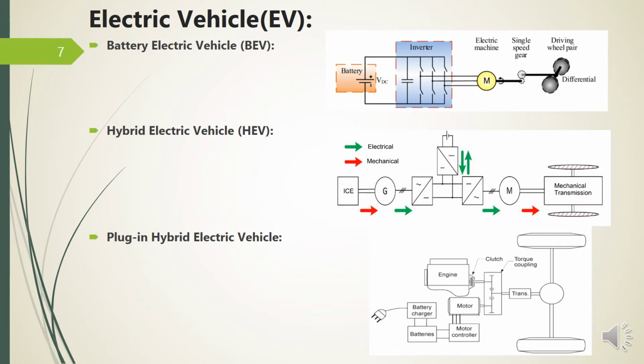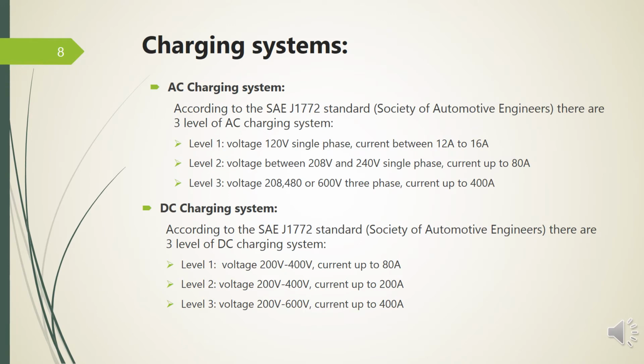Plug-in hybrid electrical vehicles first start in fully electrical mode, and all their energy comes from the batteries. When the battery energy reaches a specific low level, the internal combustion engine starts until the end of the trip. The batteries can recharge through both regenerative braking and plugging in. According to the Society of Automotive Engineers, we have two standard systems, AC charging system and DC